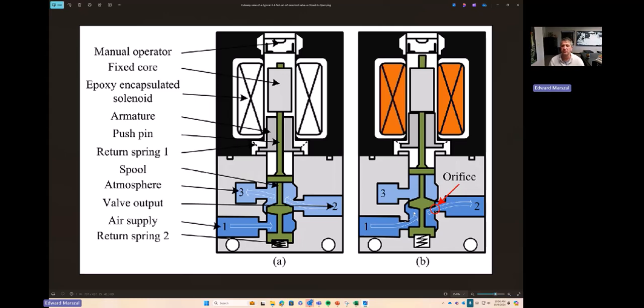Nobody's. You have to understand that a company that's using 24-volt DC solenoid valves that have undersized coils on the Gulf Coast of Mexico is going to have a spectacularly higher failure rate than someone who's using 120 AC solenoids that are oversized in Lima, Ohio. Those failure rates are not going to be comparable. They're probably going to be an order of magnitude different. So let the buyer beware.